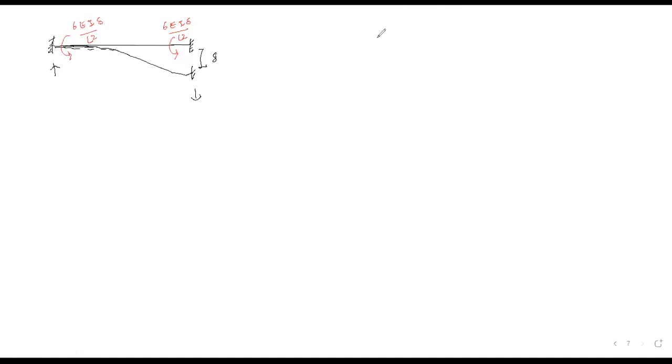Fine, चलिए. So we can say this is stage number D. In that case, what can we write here? Maintain fixity of A and B. Provide downward deflection at end B. Okay, what can we write here? Maintain fixity of A and B, provide downward deflection at end B.